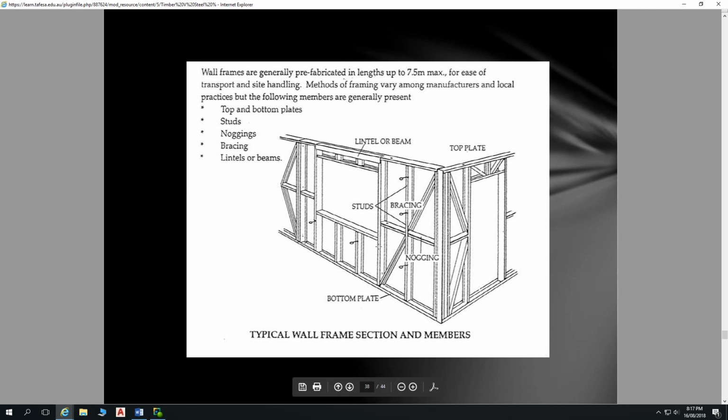So all these components, all these wall sections come out stacked on truck. You've probably seen them getting around on trucks, just big stacks of these wall frames, trusses, etc. The whole thing comes out, hoisted off the truck, left on site, and then it goes up. So very, very quick, and also once again very little wastage. These frames are made from fairly thin pieces of steel, so 0.8 mil base metal thickness. It just comes in big steel rolls.